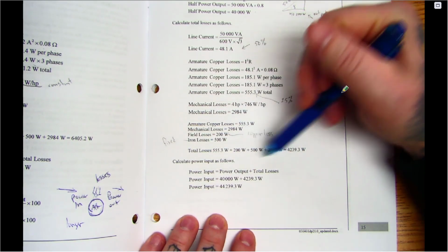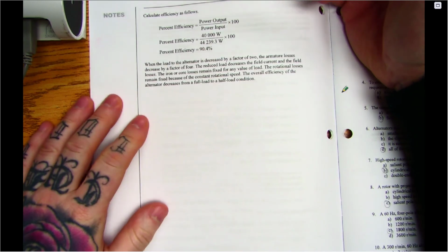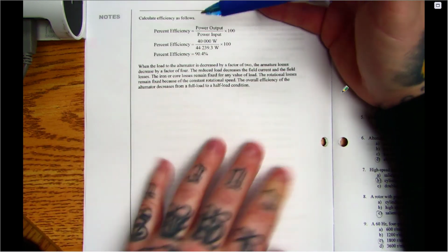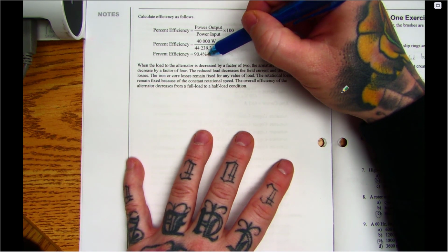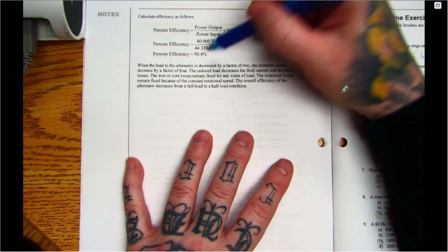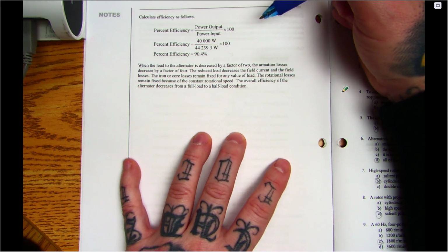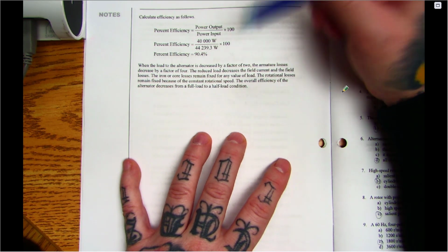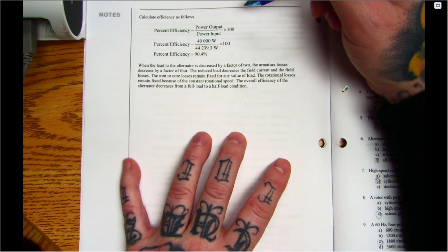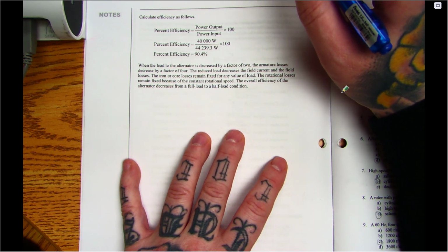So again, we get all our losses, get our output over our input, and in the module, they show you this calculation. Okay, the important thing to notice is that our efficiency went down when we were loaded at half of what we were for our full load. It's again because these machines are designed to operate at full load. That's what they're rated to do. So if we put less load on them, they're not going to be as efficient as they would if they had full load on them. Seems kind of crazy, but again, we have to have an understanding that's what they're designed to operate at.